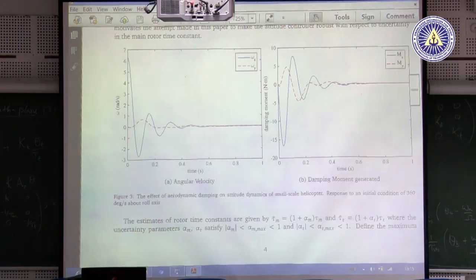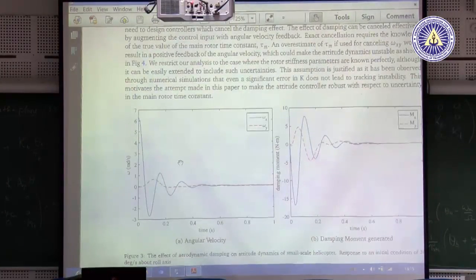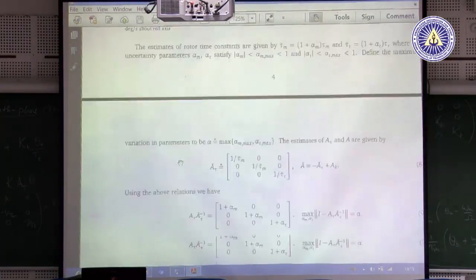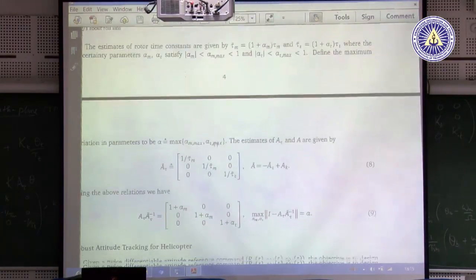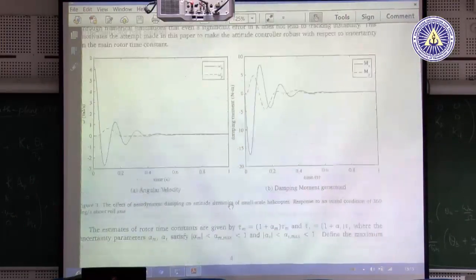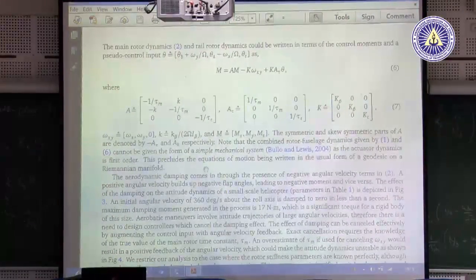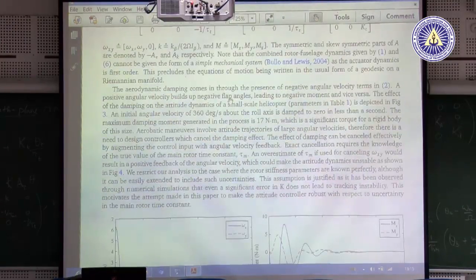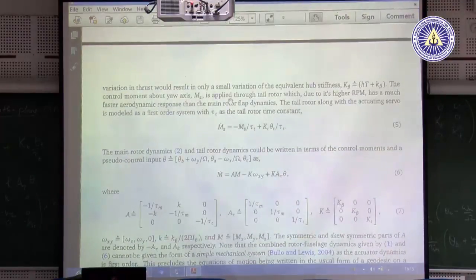The reason why I have perturbation in y because of x is the cross coupling in the moment equation. That's primarily because of the cross terms in A. This k term is responsible for coupling the moment in the x and y directions, and also the angular velocity coupling.